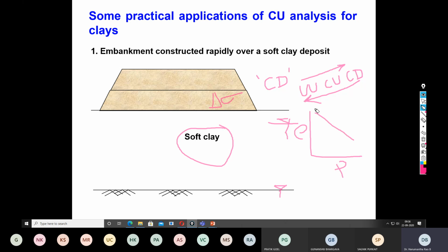No, sir. Why? Because after getting some load, the soil particles are rearranged. So they will not go to the initial state, but yes, the void ratio will increase again, but not to the initial state. There will be some rebound, but it will not reach the initial void ratio.